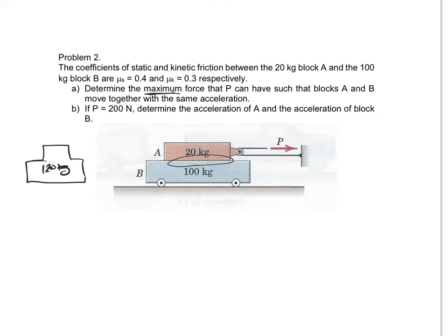So what would its free body diagram look like? Well, we would have the weight acting down, the normal acting up, and in this case we would have P and P right there. So looking at them together, summing the forces in the x direction, I'm calling x to the right, would be 2P, and that would be equal to 120, right? Sum of the forces in x equals mass, 120, times acceleration in the x.